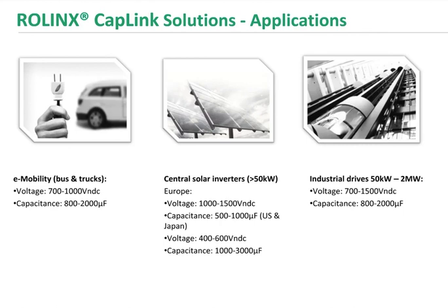For inverters, definitely solar inverters, large inverters above 50 kilowatt. Depending on the region, for the US and for Japan, we see capacitance between 500 and 1000 microfarad, with a voltage range between 1000 and 1500 volts.